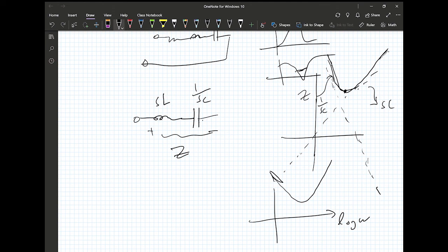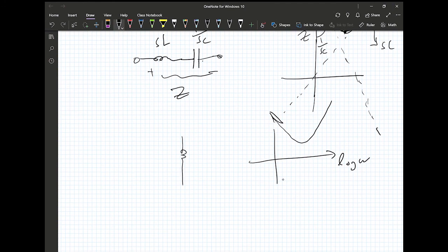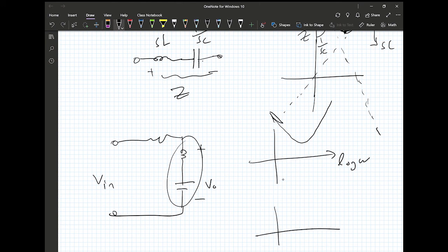and this allows us to build a bandpass filter, right, using this basic LC combination, right? Because if we do this configuration, and this is Vn and this is plus minus Vo, what happens here is that at a certain frequency range, the impedance is going to be minimum.